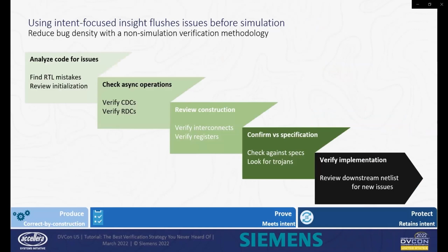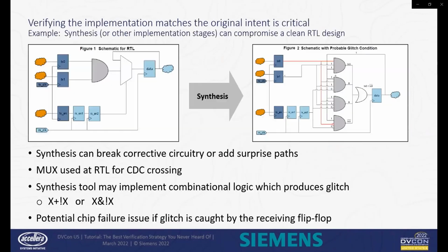Having considered how a design can be verified to implement just its specification and nothing extra, let's move on to the last capabilities of an intent-focused verification methodology, that of ensuring that the intent is still met throughout implementation. Let's begin with synthesis. On the left side of this diagram is a properly implemented clock domain crossing synchronization scheme.